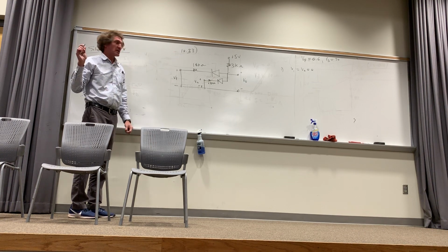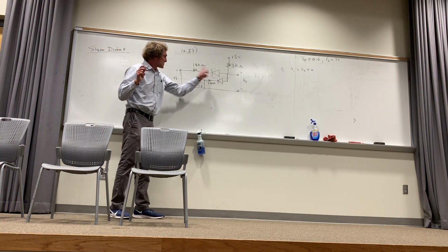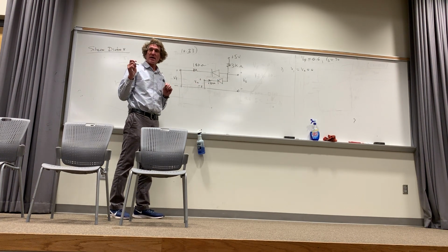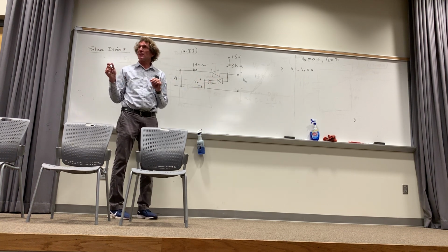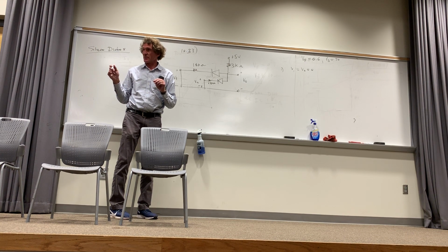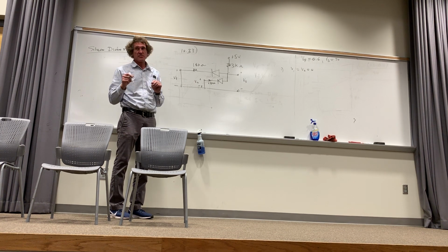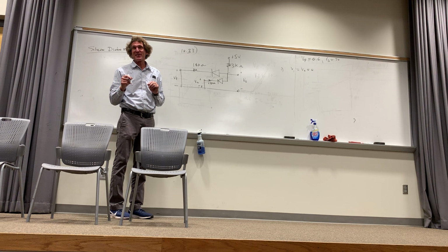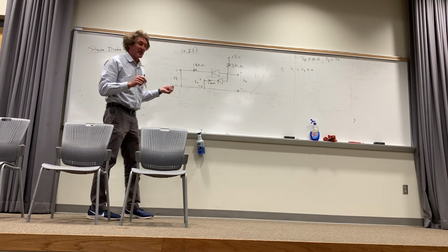Now, look at this for a second. When I look at this circuit and this circuit, they are identical, aren't they? In terms of, I should say, from here to here and here to here, that's the same configuration, a diode in series with the resistor, right? They both go to ground, right? I was just curious, is that 30 ohms or 30 kiloohms? 30 ohms. RS will never be 30 kiloohms. I mean, in any diode. It should be less than 1 ohm. Ideally, you would like it a lot less. 30 is a lot. That's a very small diode.